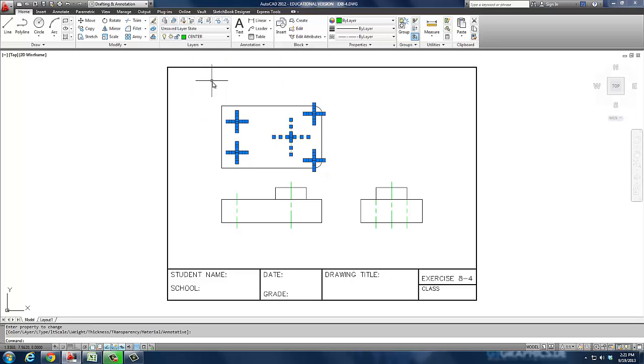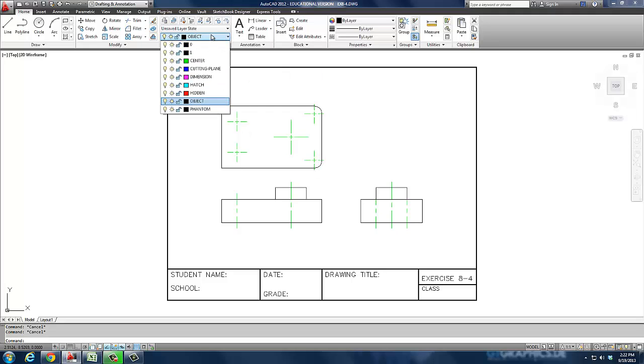So I'm going to pull it down and put them on the right layer, so I actually have things color coded correctly. All I did was highlight them, and then I pulled the bar down, the object bar, and selected the layer I wanted to move that stuff to. That's one of those easy tricks we don't always show everybody. So what we're going to do next is go in on this assignment, and we're going to turn on our O-snaps, and we're going to draw a few things.